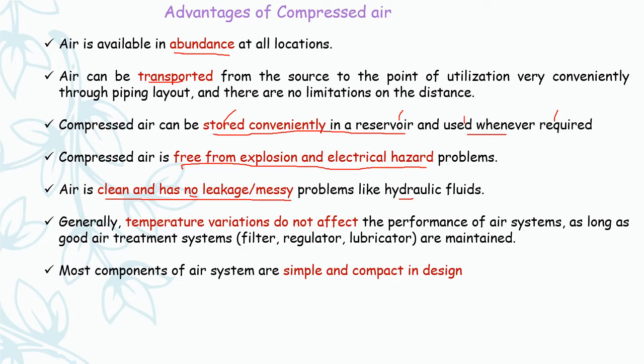Generally, temperature variations do not affect the performance of air systems as long as good air treatments such as filter, regulator, and lubricator are maintained. And most of the components of air system are simple and compact in design. In the first slide itself, you might have seen a simple pneumatic system to control the actuator. See the size of a hydraulic system and see the size of the pneumatic system. Pneumatic systems are simple and compact in design when compared to hydraulic systems.